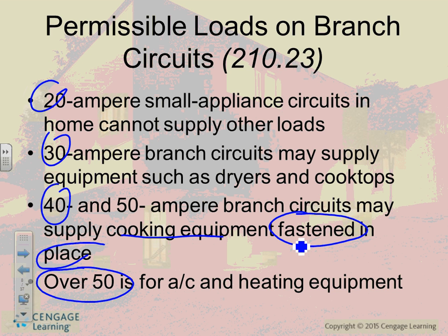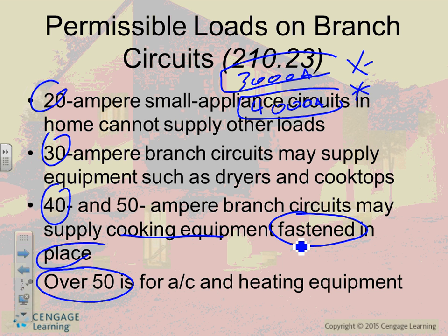Typically, the only limitation, guys, that utilities have in our area, and a lot of utilities, is they don't want you to go higher than a 3,000 amp service. Sometimes they push it to 4,000 amp. And who decides these limitations is the utility. Now, what happens, Brandon, if you need more than 4,000 amp for this hospital?